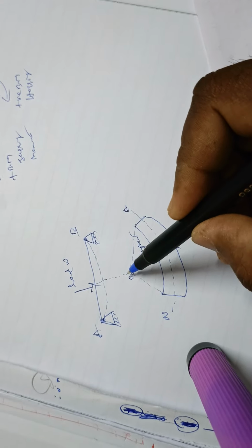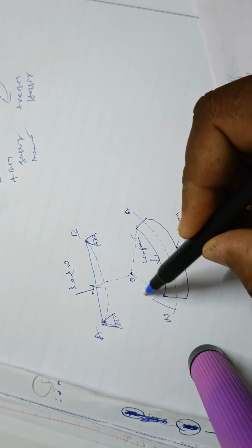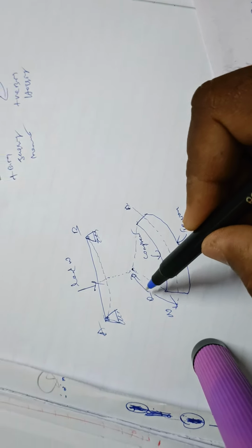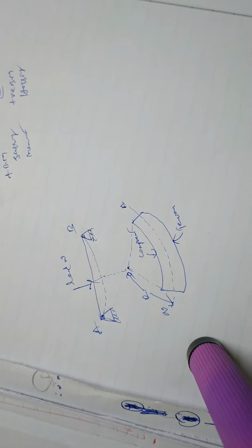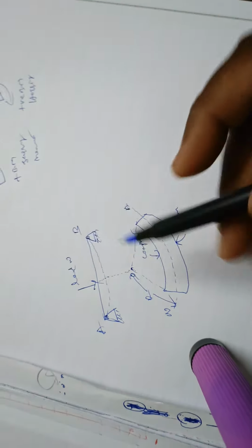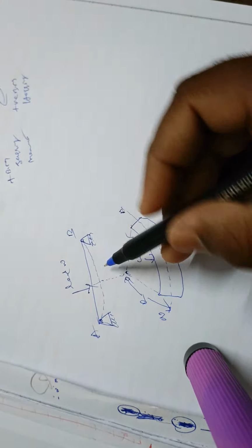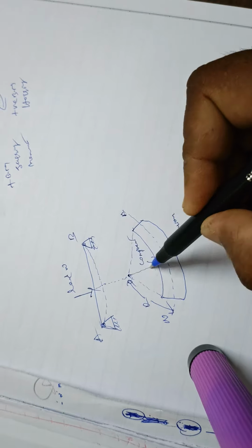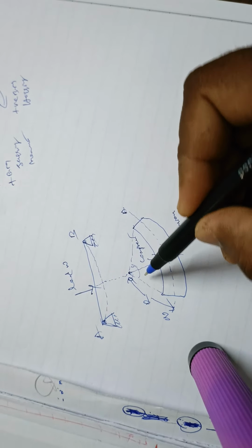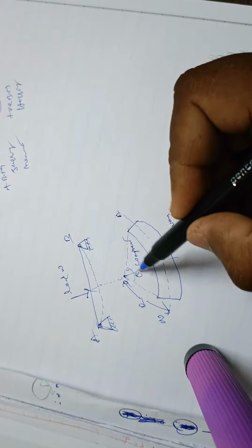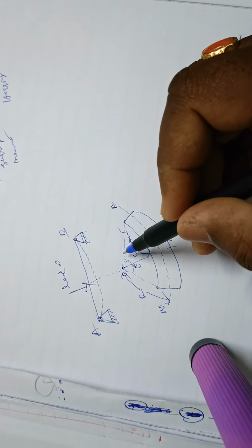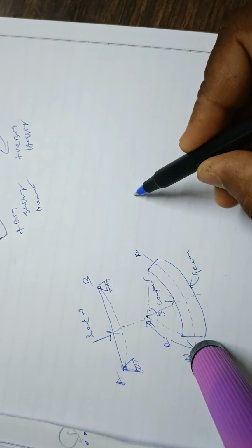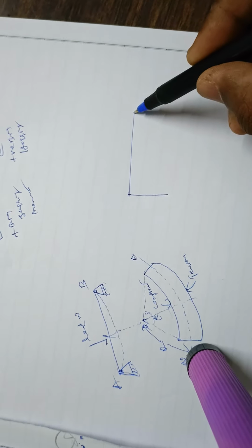Okay, so here we state the length from the center of the neutral axis at the point O as R. So this is known as R. This R is also called the radius of curvature of the beam, and it is measured in mm. Okay, and this is the neutral axis, and here the point O will determine the angle, so this will be phi or theta. So whatever the angle is in this condition. Okay, and some examples are also there. So how the bending will be done here, you can see here a cantilever or simply supported beam.